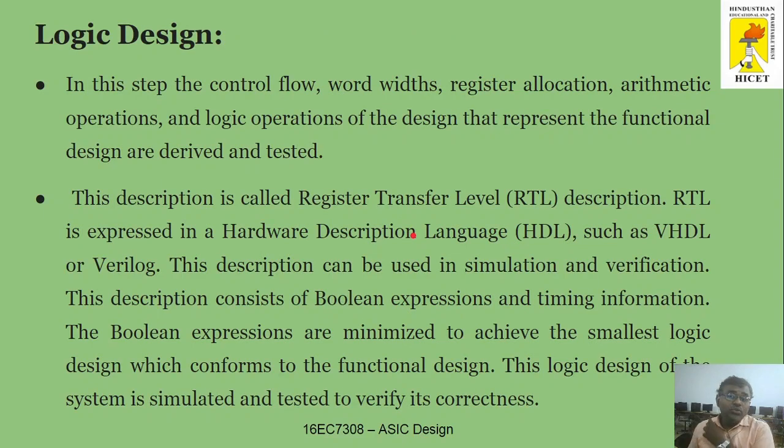So in logical design, what you do here is that you will write the program. As I told you, you will be writing the program. You can write the program in two different ways, that is, either you can use Verilog or VHDL. But in general, you will be writing a program based on hardware description language, and it may be VHDL or Verilog, and then generally we declare it as RTL, register transfer level.